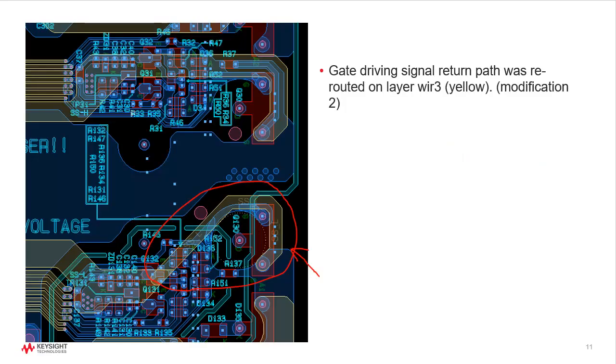So the nice thing about the digital twin compared to the physical prototype is you can modify the virtual prototype very quickly, very easily and very cheaply, and get all sorts of insights in terms of waveforms and far fields. You can slice through devices and see the field inside of devices. And let's try out a different modification.